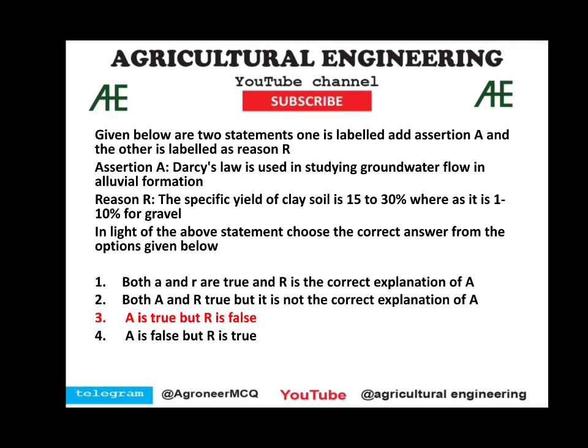Given below are two statements, assertion A and reason R. Assertion A is Darcy's law is used in studying groundwater flow in alluvial formation. This one is true. Reason R is the specific yield of clay soil is 15 to 30%, whereas it is 1 to 10% for gravel. So the reason is incorrect. So the correct answer is assertion A is true, but R is false.